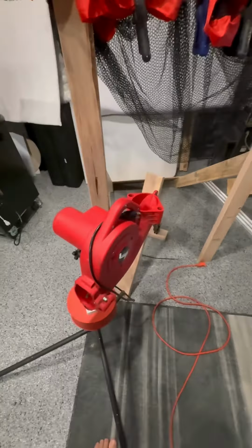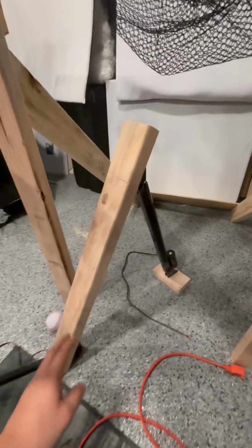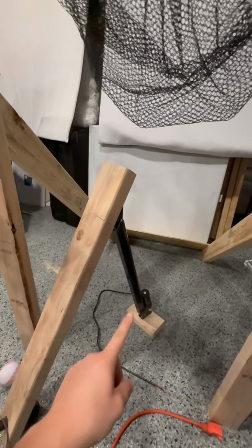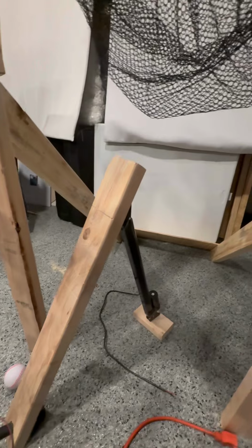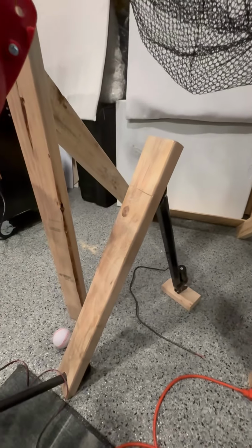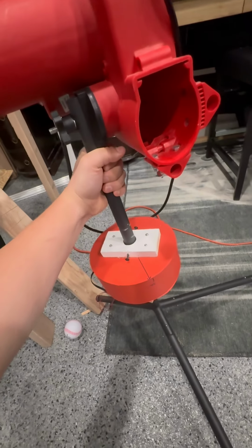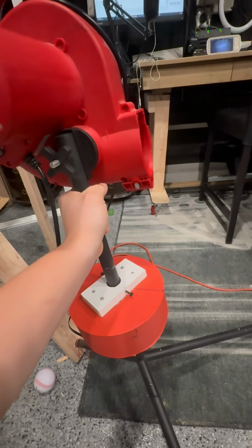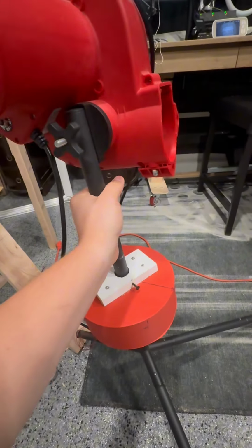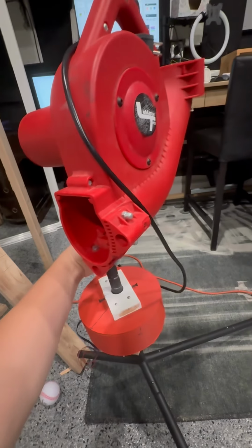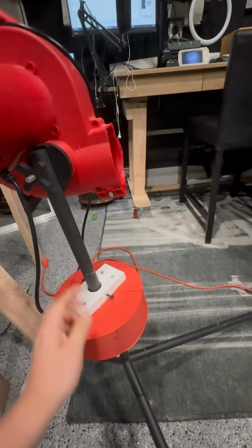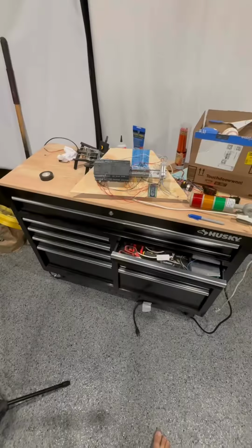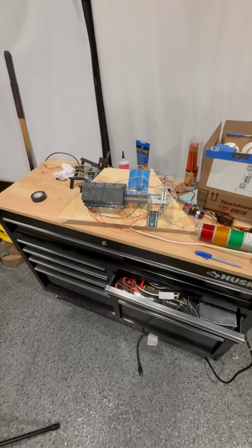The linear actuator axis is going to need one output to tell it when it's time to start moving either direction, and then a second output that's going to tell it which direction to go. The rotary axis is going to need one to tell it to start moving, and then a second output to tell it which direction to go in. And then because this could turn in 360 degrees, but I don't want to allow that, I'm going to put proximity sensors at the limits. So that'll be 2 digital outputs and 2 digital inputs.